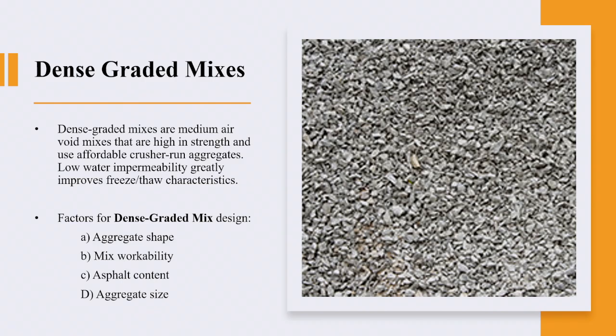You know, the more you encase your coarse aggregate, the lesser the impact of the temperature on expansion and contraction, so the better it will be in fighting the cracks. However, it's not good for ruts. So more asphalt means more money spent and lesser resistance for rutting.